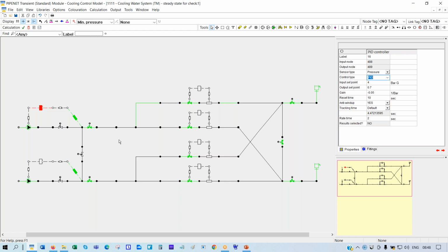But the fluid says, no, you're not going to stop, I'm going to keep you moving. So as a result of that, you get vacuum pressure in the pipes, and that vacuum pressure can make the pipes collapse when you have such large pipes and there is pump failure. So this pump failure is a very important scenario in cooling water systems, particularly the large cooling water systems.